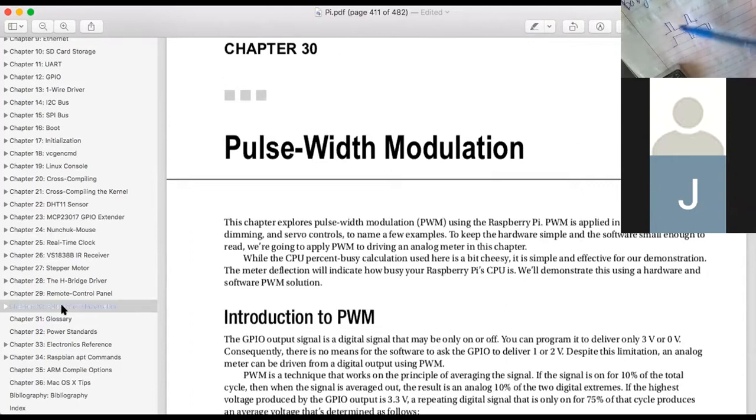When you want to drive this motor at low RPM, you turn it on for a very short time and then off for a very long time. And usually you're switching them tens of thousands or hundreds of thousands of hertz. So you switch them really fast. You are not turning it on 1 second, off 3 seconds. That will cause a problem for your mechanical drive.